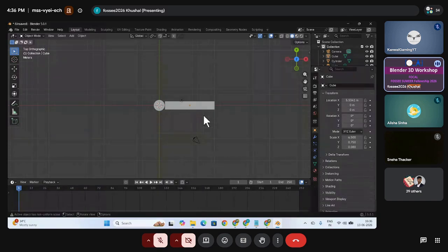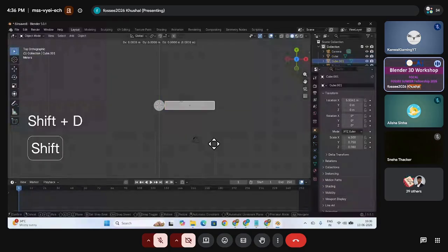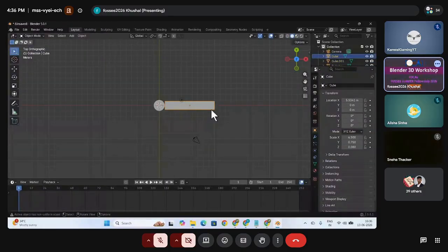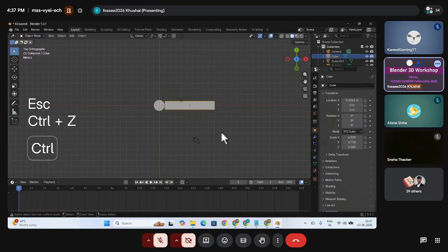So what I will do, I will duplicate it and rotate it 180 degree, and then 180 degree, so 3 blades will be there. But whenever I am rotating it, it will rotate in the center of this blade. So I click it here, make it duplicate, Shift D. So it is duplicated now. I select this, and when I am rotating it, what will happen? See, for rotating R, and when I am rotating, you see it is rotating in the center of that object, right? So escape, undo, undo.